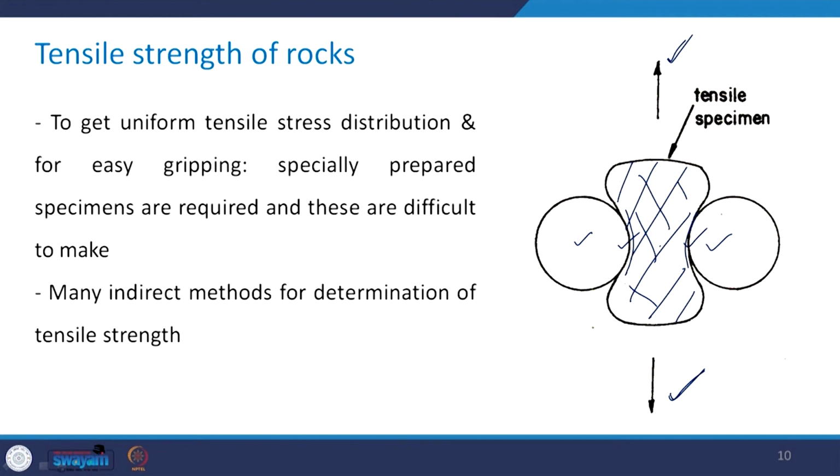There will not be uniform stress distribution all along the specimen, and the moment there is non-uniform stress distribution, whatever strength you get from the test will not give you the correct picture of the strength.